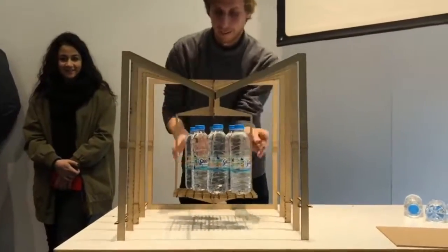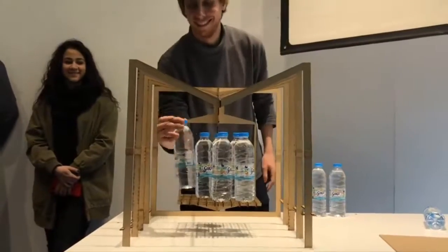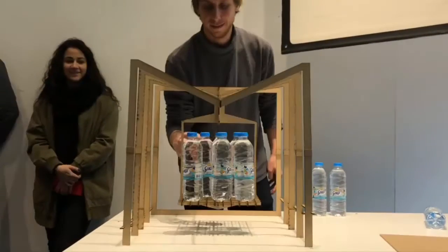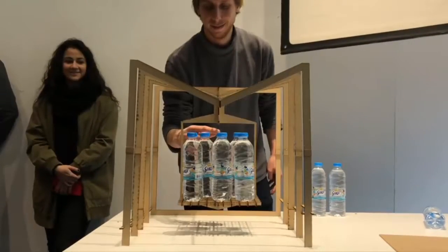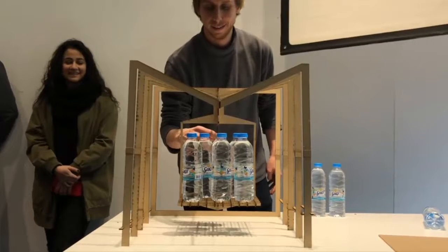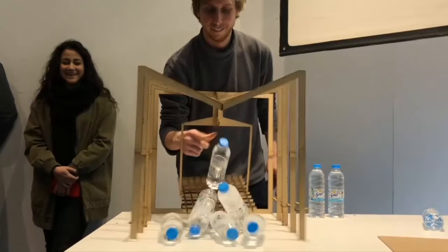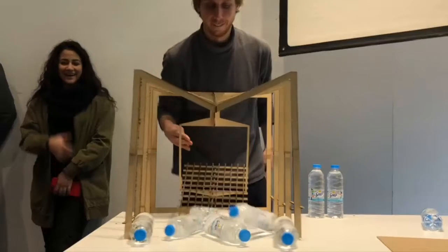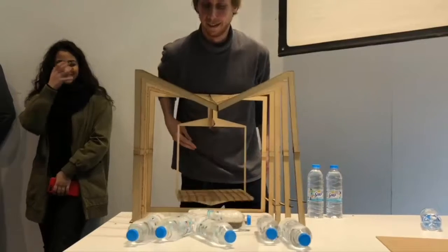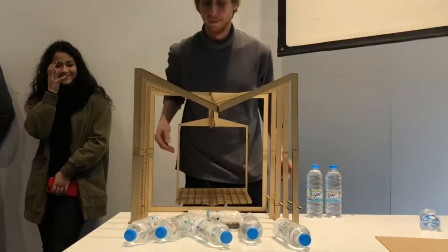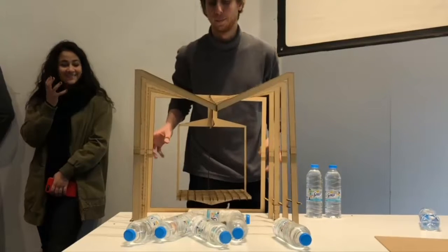Our previous model failed at the 5th bottle, 2.5 kg, due to the imbalance of the weight distribution on the platform. This is because the platform is held by 3 vertical wood structures rather than 4. Thus, when the pressure is applied in the middle, the platform deviates downwards on the side with the 4th support missing. This in turn leads to the opposite side snapping.